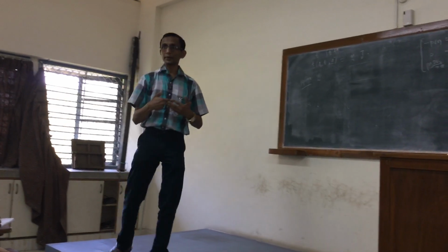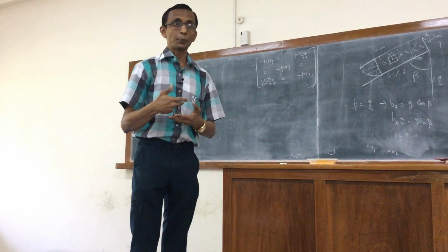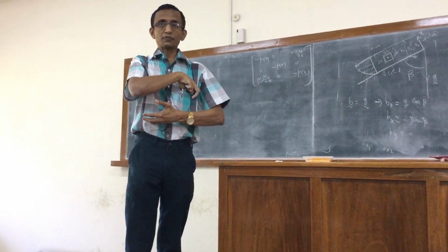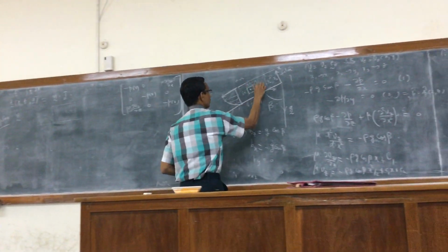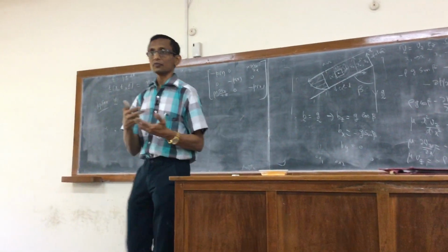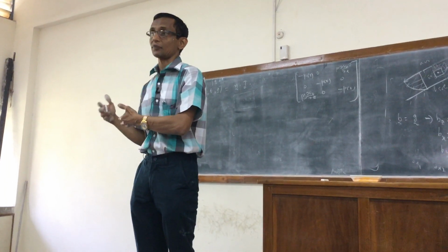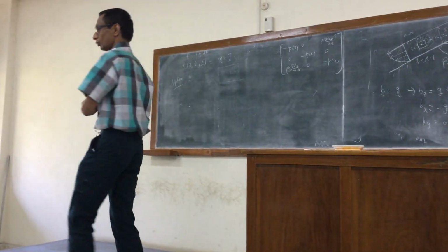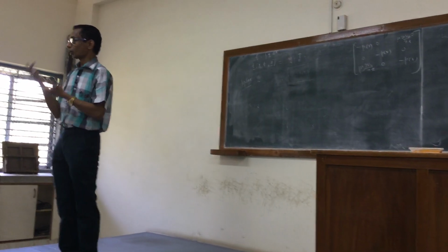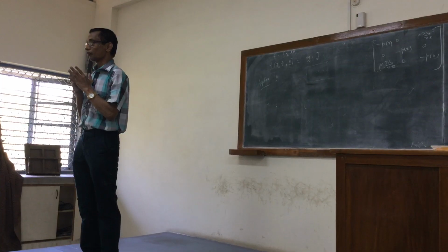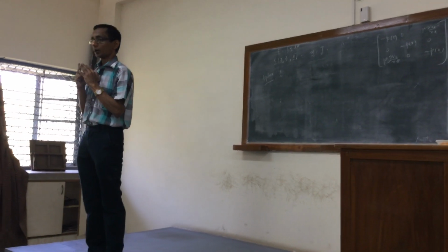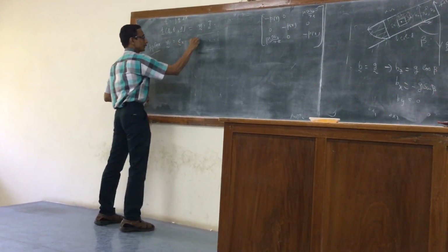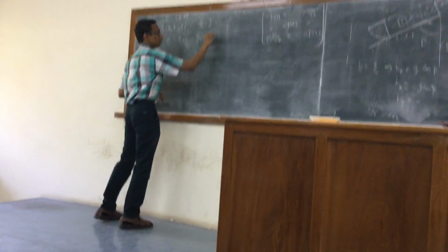So I need to calculate the contact force at every point, but because these are planar, I can also consider a spherical volume of fluid. But for convenience, I have chosen it to be a rectangular volume because that's what we have dealt with so far. Rectangular coordinate system where this is easy to implement, right? So we know that for a planar surface, the normal is the same at every point. So for the top face, what is the direction of the outward normal? Ex, right? So n is equal to Ex. So what is Ex dotted with T?